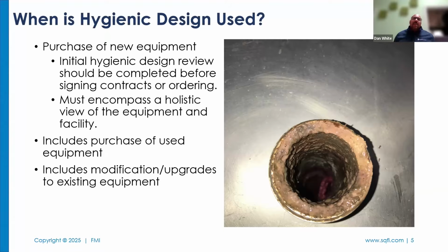And the reality of issues when it comes to hygienic design is that it's not something that shows up immediately. You don't usually start getting those counts right away. It's a week, a month, 3 months later. You look at this pipe, I have no idea when that pipe was cleaned, but that is not a couple days' worth of buildup inside that pipe. So yeah, those are key elements.